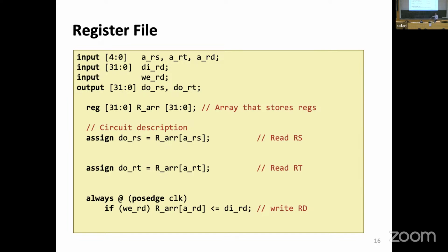Now a little bit of a trick. This is like the simple form. Then we go and look at the MIPS architecture description, and they say you do have 32 registers, but not all of them are the same. Some registers are more equal than the others. Register 0 is special, it always contains the value 0. How could we do this? Well, one way would be to discipline everyone on Earth and say, if you're writing MIPS code, compiler guys and assembler guys and hackers and everybody who wants to break into systems, make sure that the value 0 stays there.